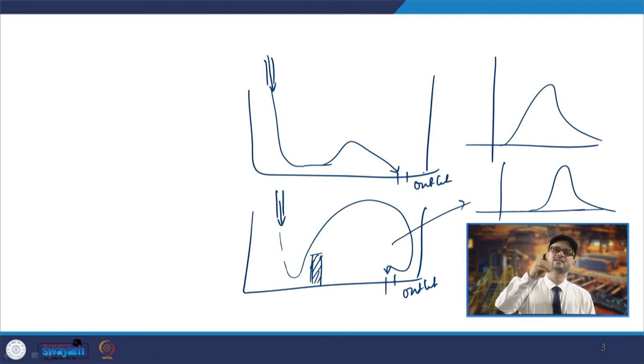Depending upon the flow pattern inside the tundish, how the liquid is going to flow, and when its concentration at the outlet can be monitored properly, that can be understood with the help of these C curves. So, these are the uses of the F and the C curve, which are used for the flow characterization in the tundish.